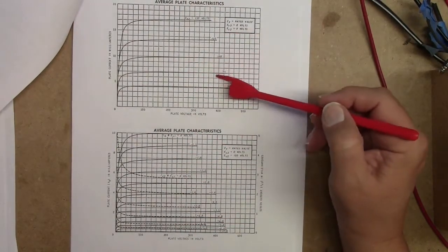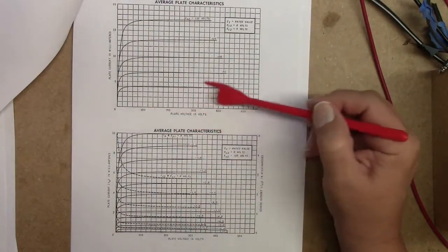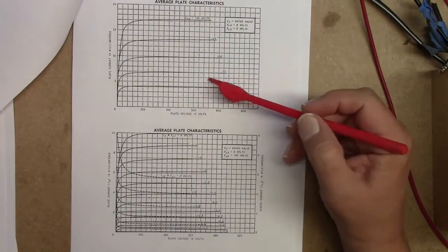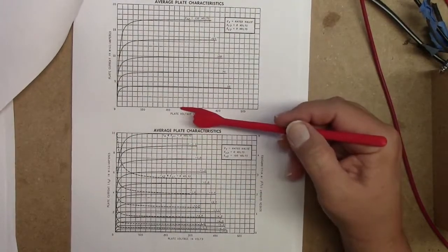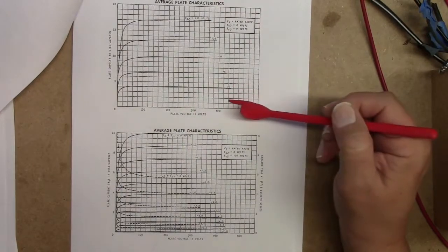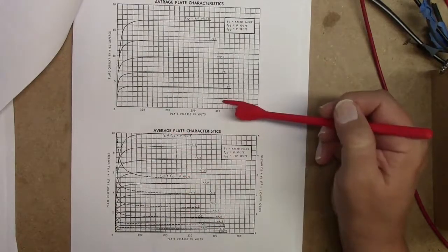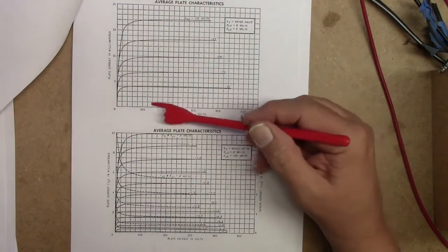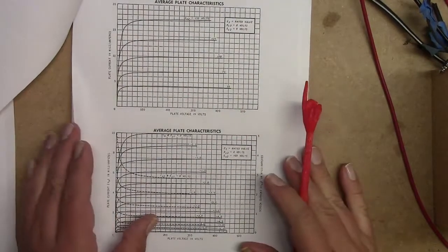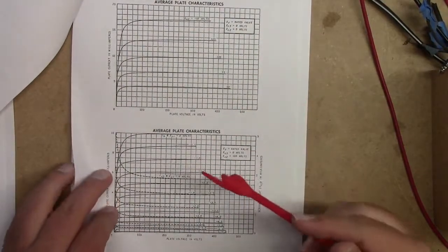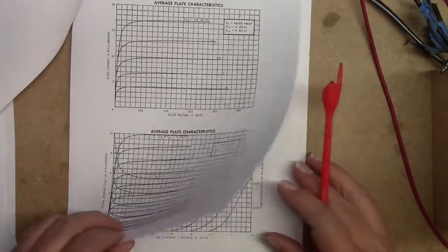If you were to lower it down to 75, all these lines would smash into this area. And if you lowered the screen even more down to 50 volts, all these lines would fit into here. So we're at 16 volts, so our line is basically way down here. So all these lines are going to fit in this little area down here, which makes it pretty difficult to do anything. So with low screen voltages, these curves don't really show you what you want to know.